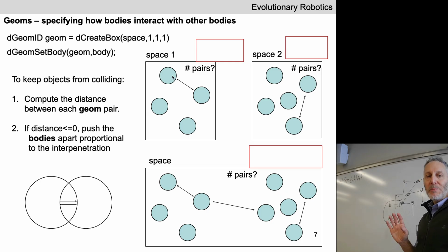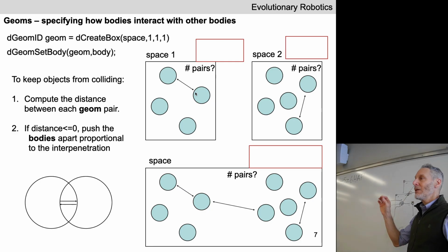We're going to assume that we've placed 4 of these ball bearings in one contact space and 5 of these ball bearings in a second contact space. And what a space does, any objects that are inside a space, at every time step, the physics engine is going to look whether any pair of objects in that space are in contact with one another.